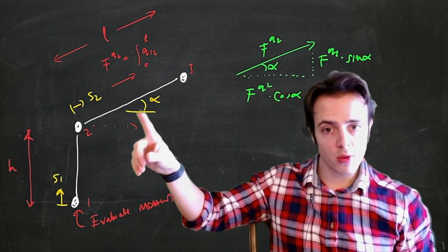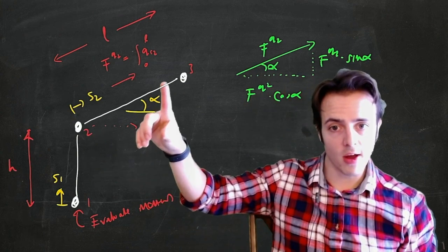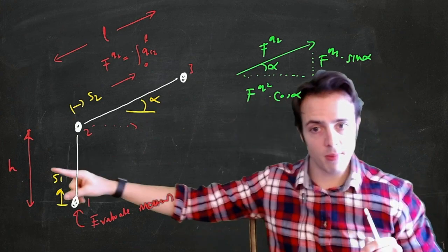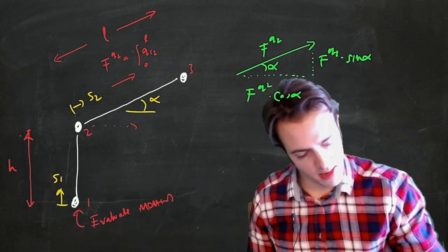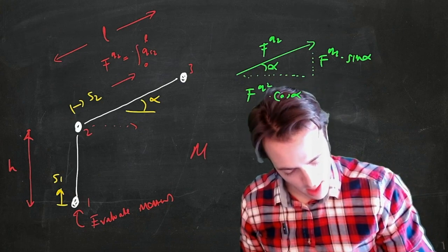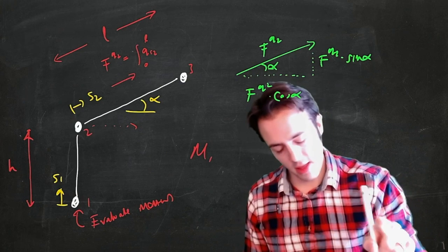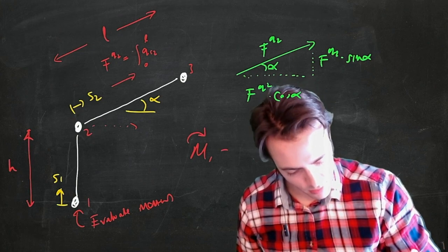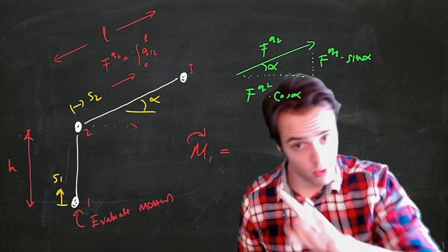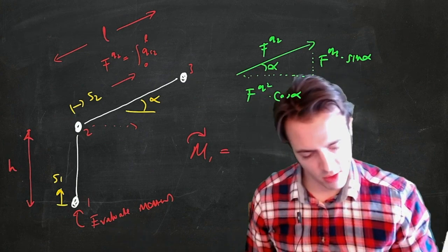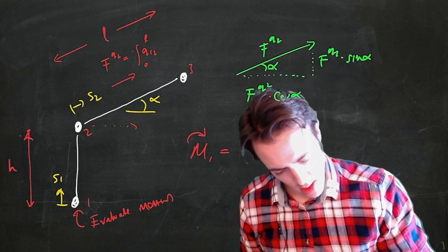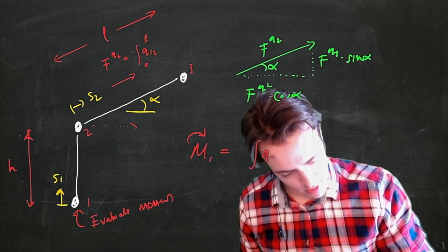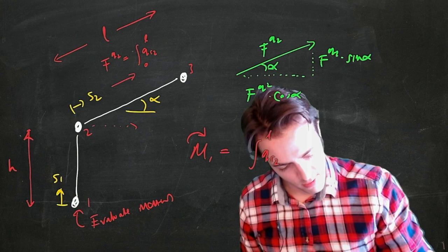So the moment produced by this shear flow is equal to this bit multiplied by this moment arm. Okay? So let's say M1, and let's say the moments are acting counterclockwise, would be equal, for this completely made up shape that I've just produced, to the integral of QS2 from L to 0.